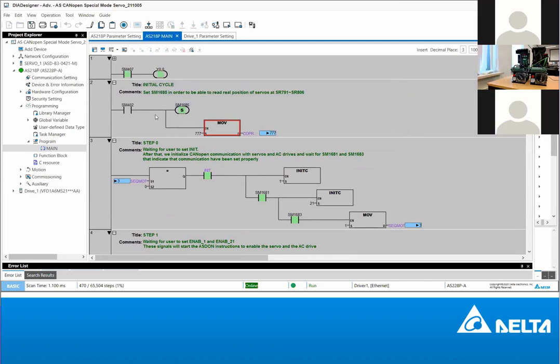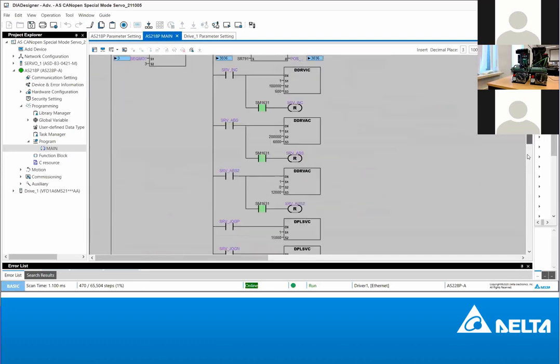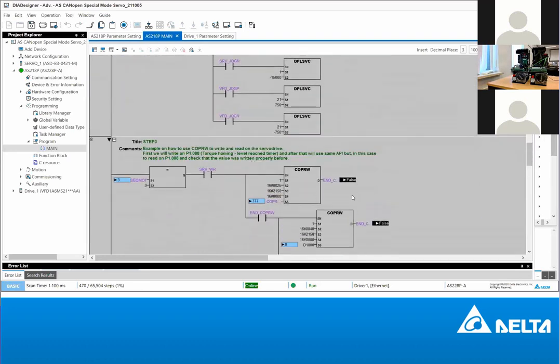So you see, when we started the program, we initialized the program, and then we send 77 to this variable. That is why you see 77 in network 8. Let's go to network 8. I'm there. So that's why you see this 77. So we could change it later.